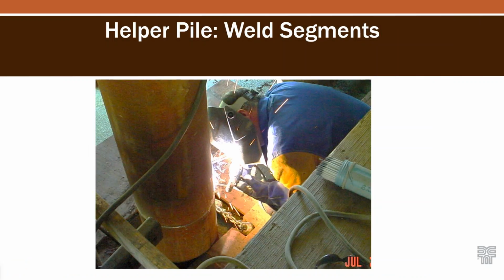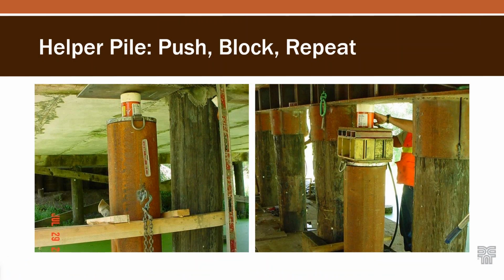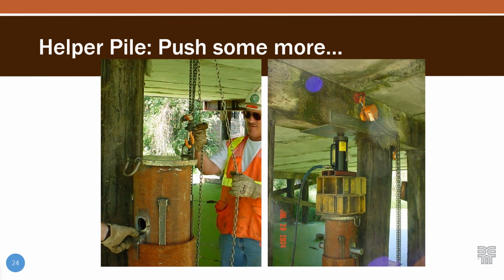So getting a good weld on that. And then here we go, push, block, repeat, right? That's the system. You just keep doing it over and over. Unlike pile driving, you don't have quite as much control over the pile where you can have leads on it. So paying attention to what you're doing here and making sure you keep the pile straight is important. And then here they are just kind of blocking and redoing it again.